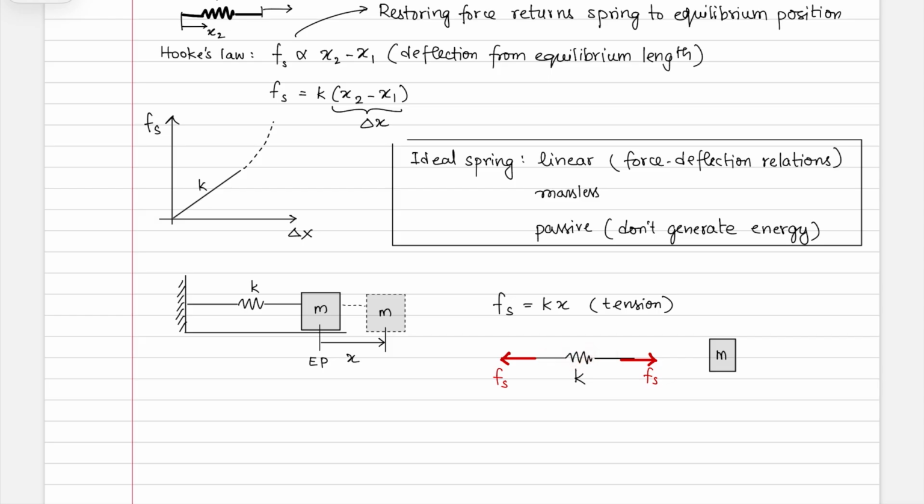And so if you were to have the sum of forces in the free body diagram equal to the sum of forces in the kinetic diagram, which I hope you're familiar with, the kinetic diagram accounts for the inertia, then because there is no inertia, the right hand side will be equal to 0, which means that the net forces on the spring must be equal and opposite, which is why this here would be equal and opposite.